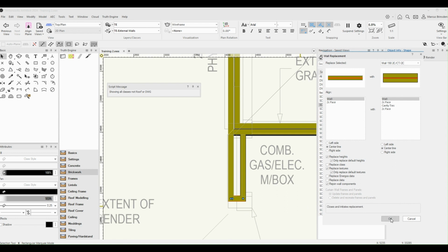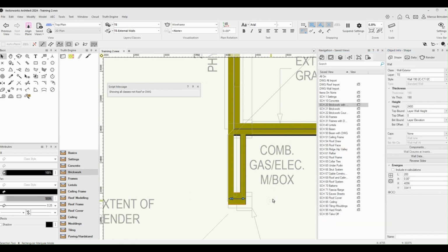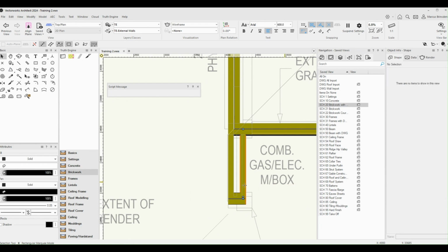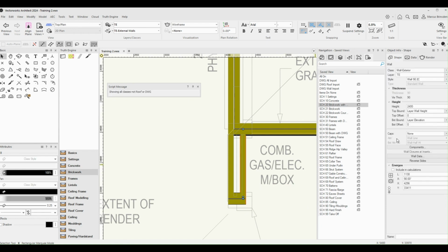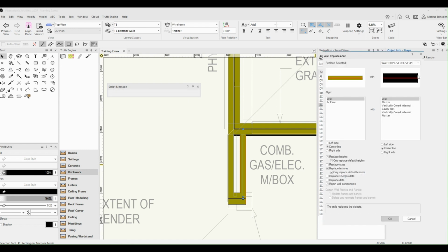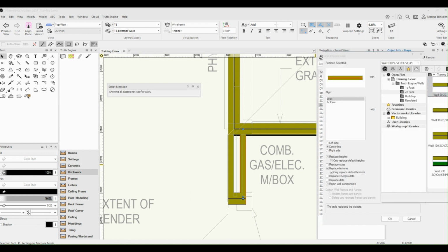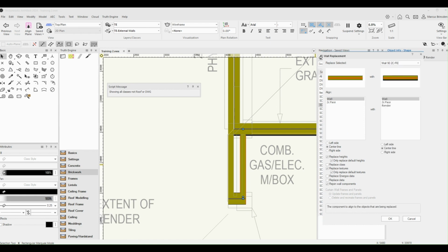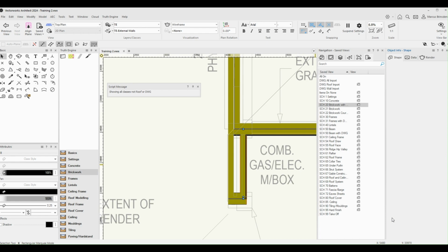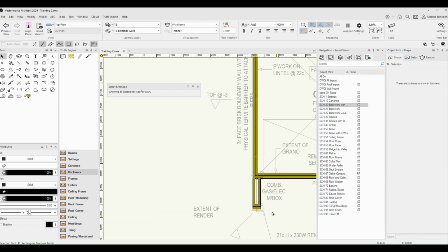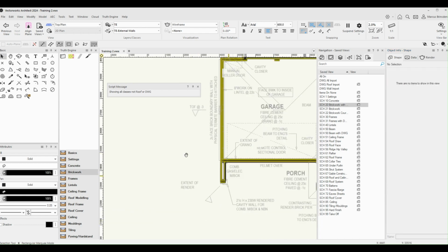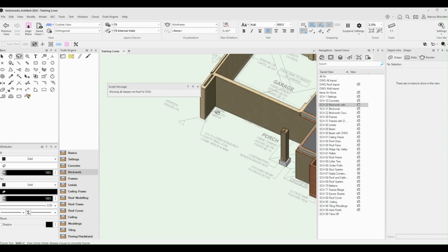And we'll go down the middle. Okay. And this side needs render. So we'll change that to 2 face with render. So then we'll make the reference line down the middle of the 2 face. There we go. That will give us that render through there. So that's pretty close to what we'll need there.